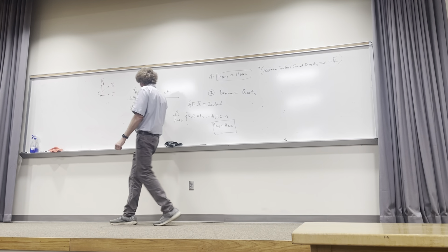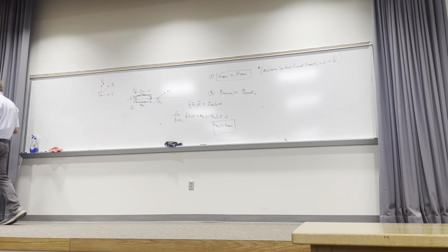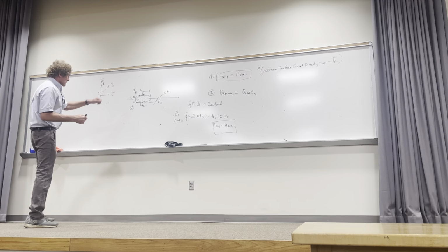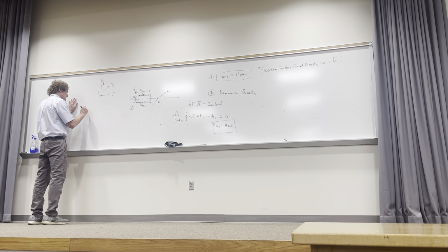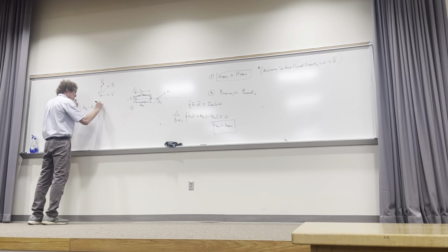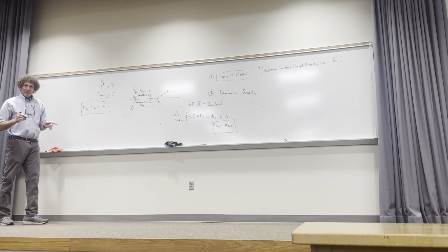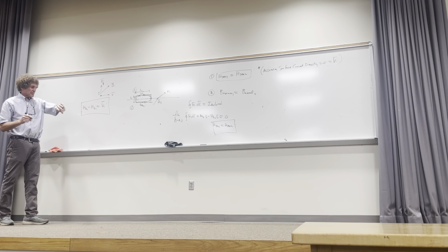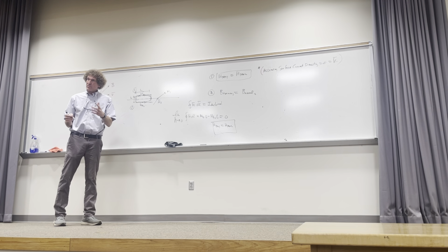Now, if it's not 0, if I put a surface current density in there, then the easiest way to get it is H tan 1, where you take H tan 1, or the tangent field in region 1, minus the tangent field in region 2, and that will be the surface current density K. I'll talk more about that with some examples in a bit, but that will work for surface current densities. Normally, H tan 1 is H tan 2, almost always.